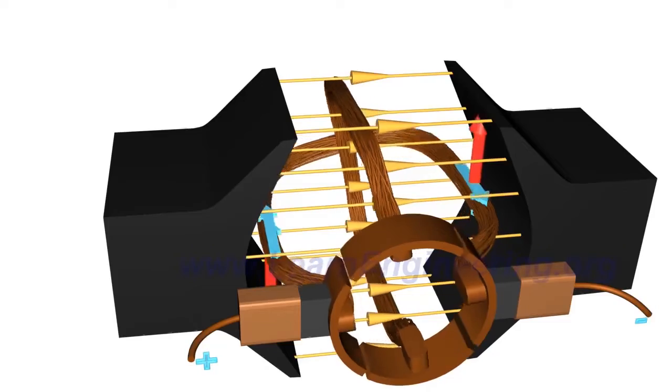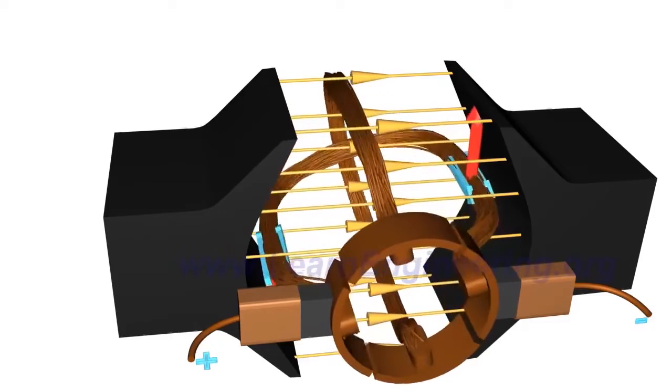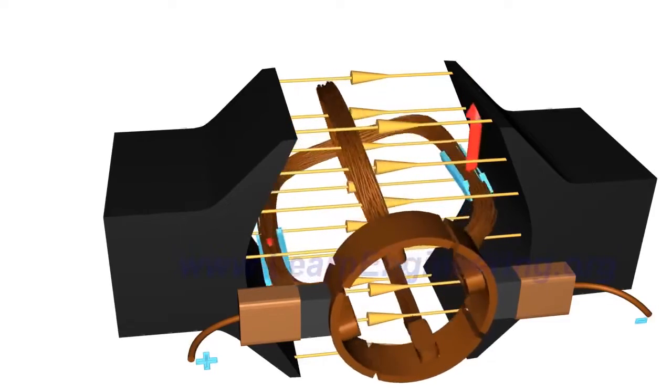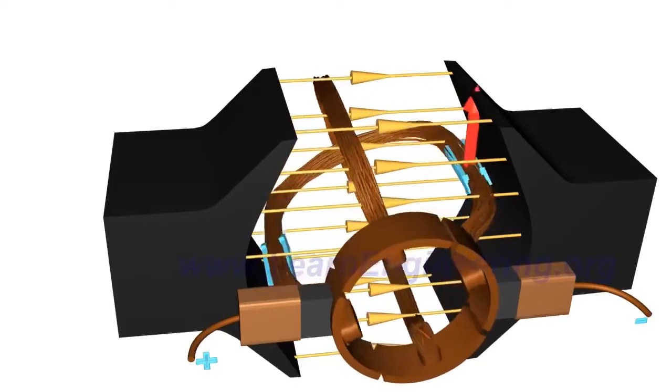In this arrangement, when the first loop is in the vertical position, the second loop will be connected to the power source, so the motor force is always present in the system, and the armature conductor in the 270 degree and 360 degree positions will follow the same action as well, and the commutator is made segmented to achieve unidirectional torque.